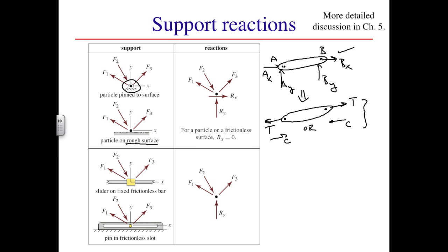It is also the case that we will run across problems with elements mounted on or in frictionless surfaces. In practice, we may use the term frictionless surface to indicate a well-lubricated interface between interacting components. It may not be that friction is completely absent, but rather is so small that it can be neglected. The two cases shown here differ only in that the slider or collar is restrained from the inside.